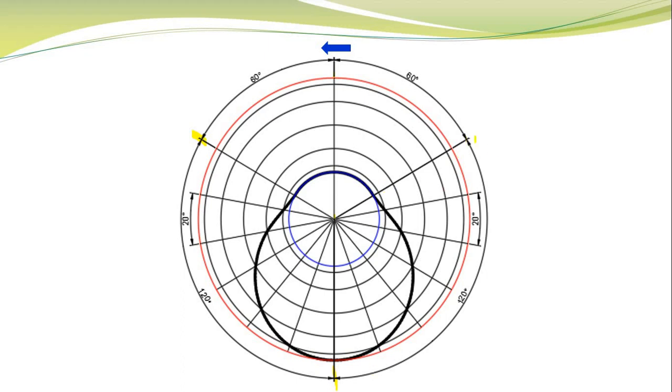So from this point to this point is another 120 degrees, right? And then finally for the remaining rotation of the cam, which equated to 60 degrees, the follower or the valve will remain closed. So these are my 4 blocks that I was dealing with. So this is 1, then from here to here is 2, from here to here is 3, and from here to here is 4.